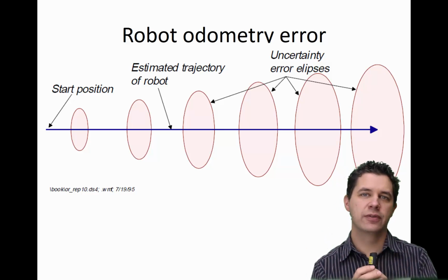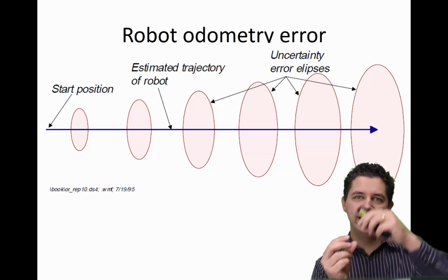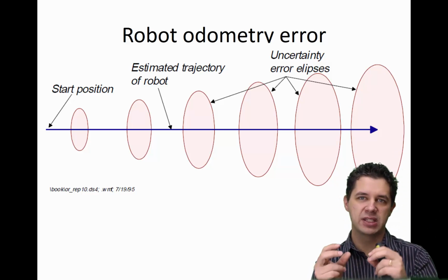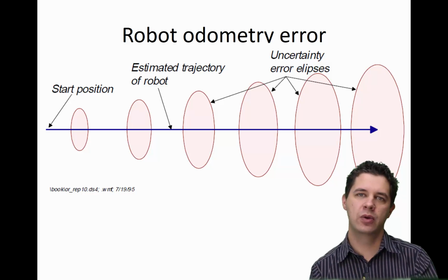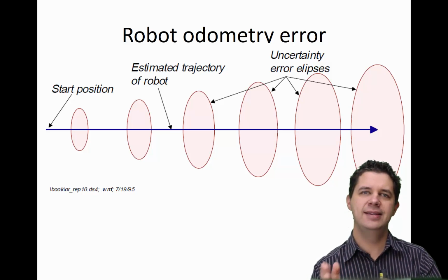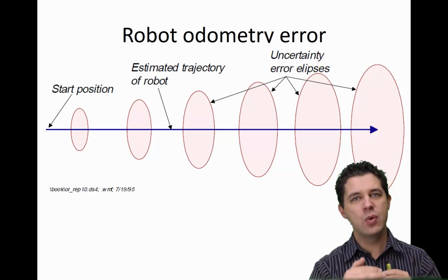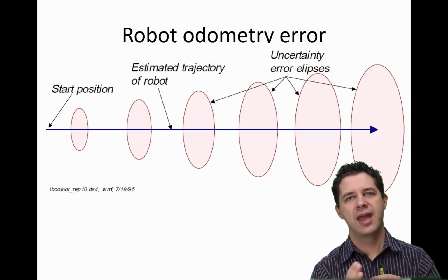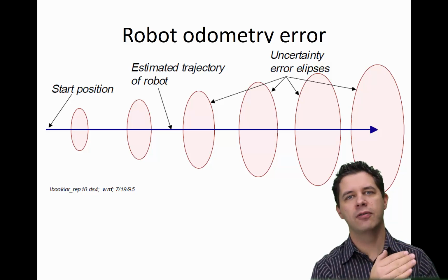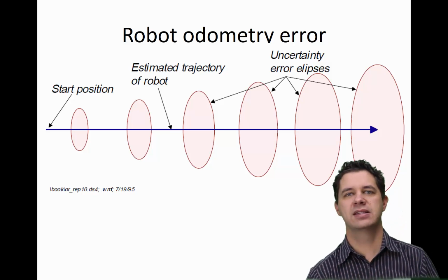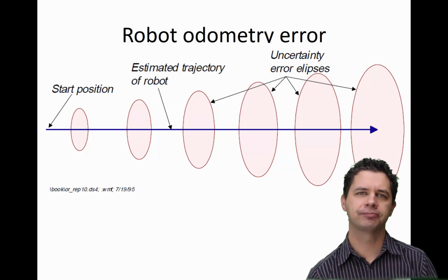The orientation of the robot is what really grows that ellipse out. And the orientation is completely governed by small changes between the left and the right wheels. And so we can very easily head ourselves off in one direction, and though we know pretty well how far that we've actually travelled, our pose may be significantly off because our orientation's been off. And that's why the ellipse is biggest in that direction.